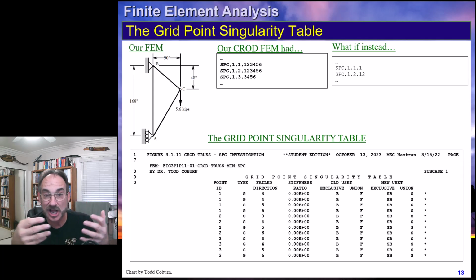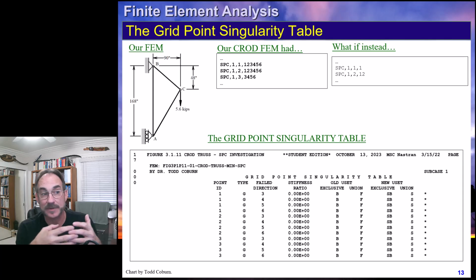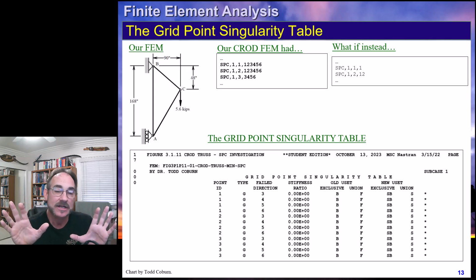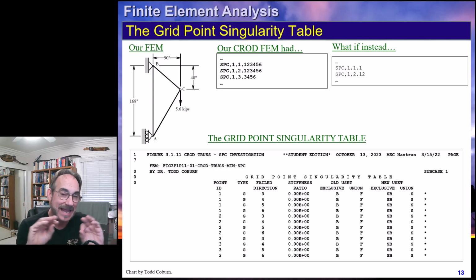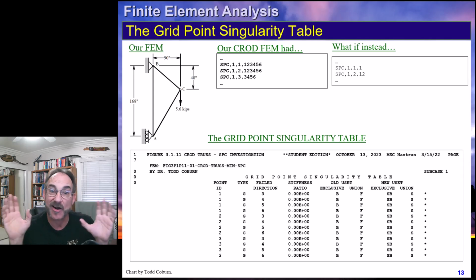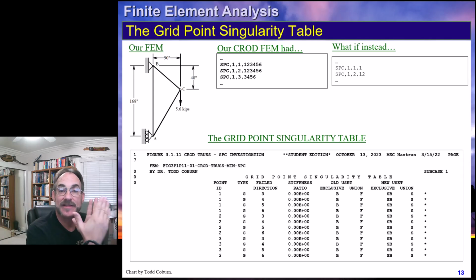Now, normally, if it's soft, you want to see it because it's going to deflect. But this is so soft that it's problematic, and it's actually undermining your solution, keeping you from getting a solution. So it just purges it as if it doesn't matter. So we purge things when they can't move, and we purge them when they aren't relevant. So purging everything in the Z direction makes sense because it's not relevant for this problem. Purging any other degrees of freedom can do the same thing.